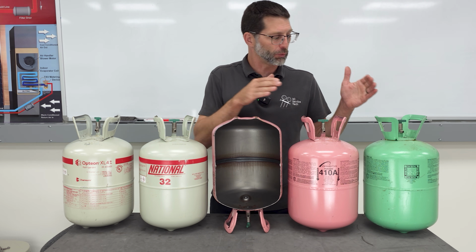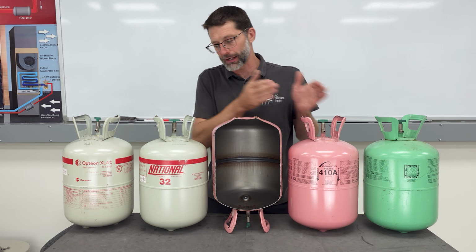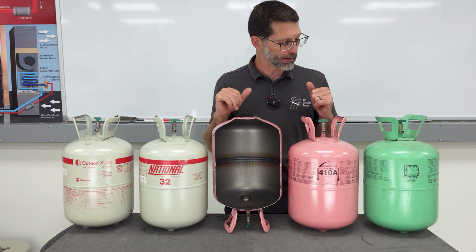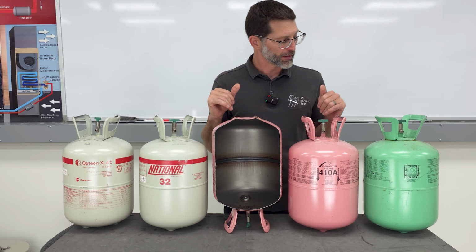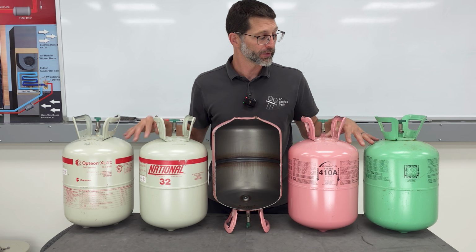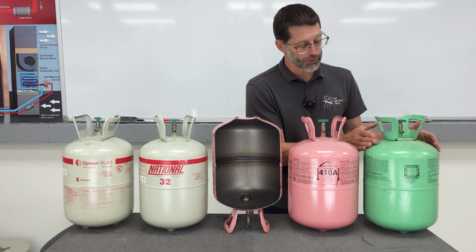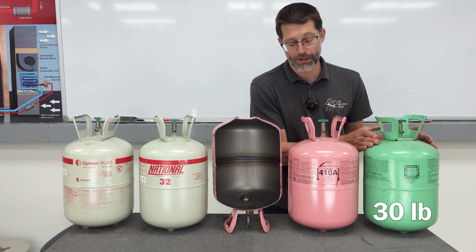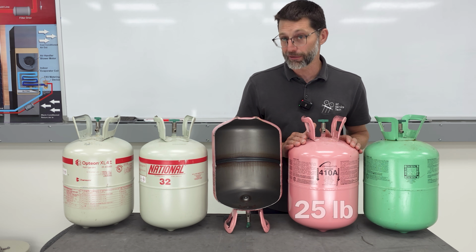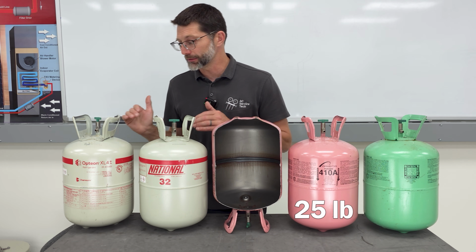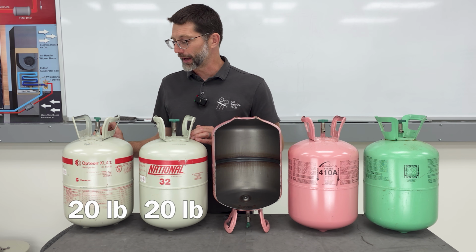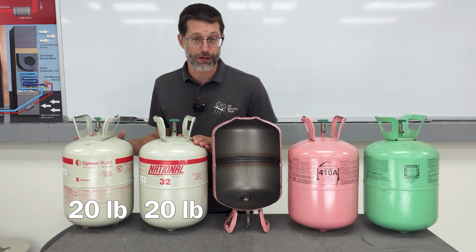Anyway, we do have other videos in reference to the ozone depletion potential and GWP and things like that, the reasons why we switch from this to this and now from this to these two. So you can check that out in the description section below. But what I want to tell you is that all 4 of these tanks look like they're the same size, right? But this tank, R-22, has 30 pounds of refrigerant inside, whereas a new R-410A bottle has 25 pounds of refrigerant inside. And these newest A2L refrigerants, these ones have 20 pounds of refrigerant inside.